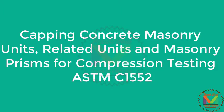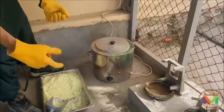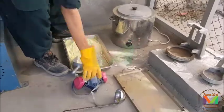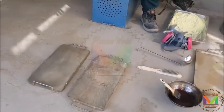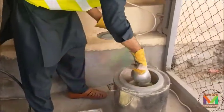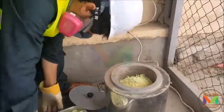Now I will introduce all the equipment according to ASTM C140, which is a warming pot for keeping the mold. We have a spoon, a sieving brush, and a lubricant for the mold, and we have 2 bearing plates, which we can also call distance spacers. High-strength gypsum cement for capping materials, and the warming pot, which is heating right now.